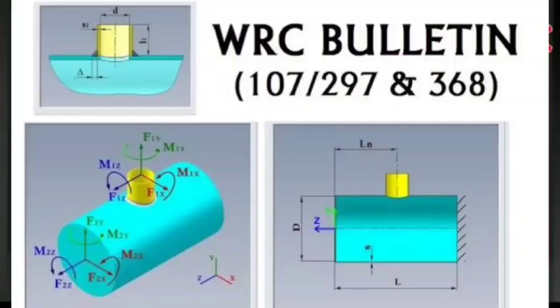Yeah, others also said the same thing. Compress is better, it gives good results. They also give reports, and the way they represent them is better, along with the requirements they consider: local load analysis, WRC 297 and WRC 107, split into load cases, that is sustain and expansion, and then the derating as per UG 44B. Which is the correct approach? If there is any basis for that given in any WRC, if you can share that, that will be great.